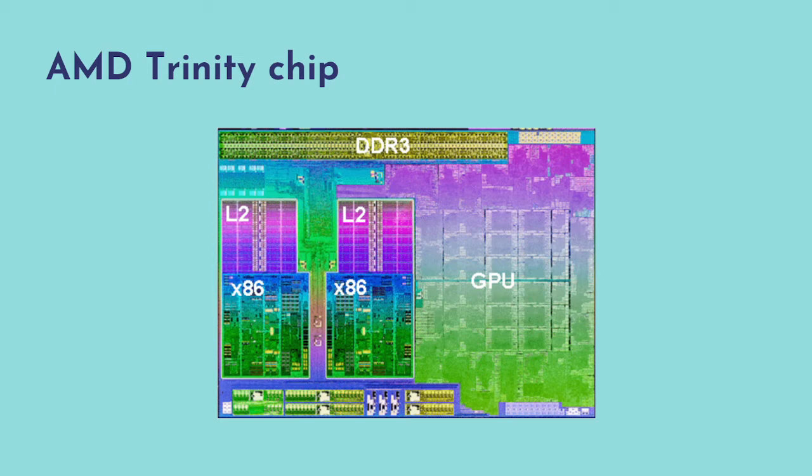Many of the improvements stem from eliminating the chip-to-chip linkage that adds latency to memory operations and consumes power, because moving electrons across a chip takes less energy than moving the same electrons between two chips. The co-location of all key elements on one chip also allows a holistic approach to power management of the APU. Various parts of the chip can be powered up or down depending on workloads.